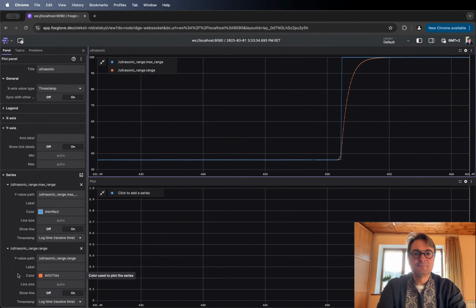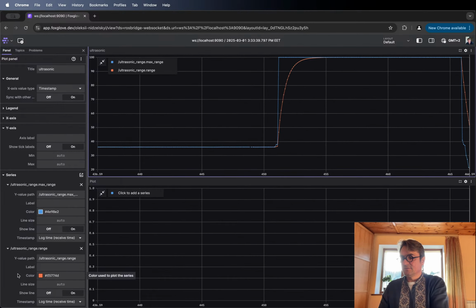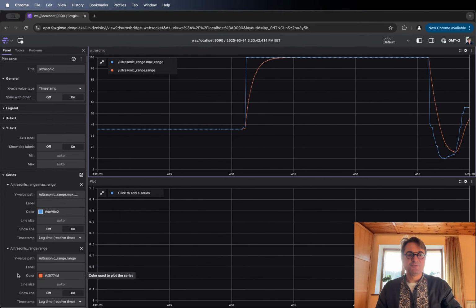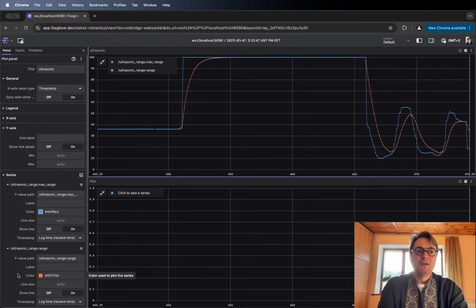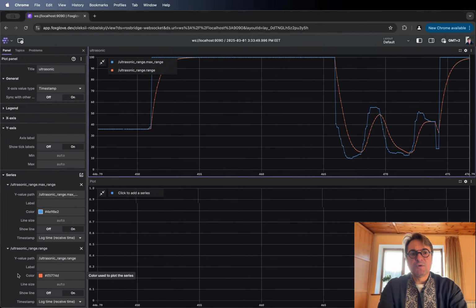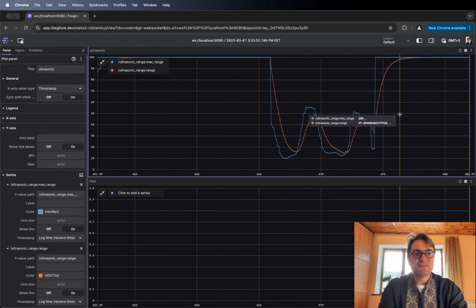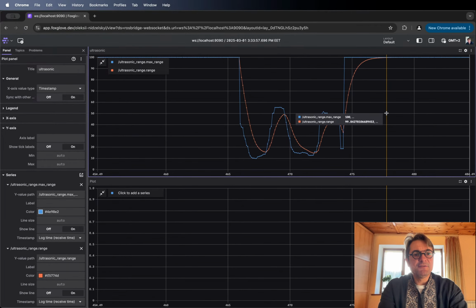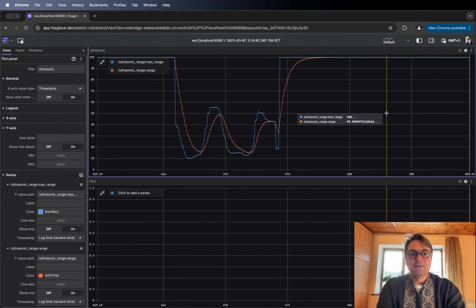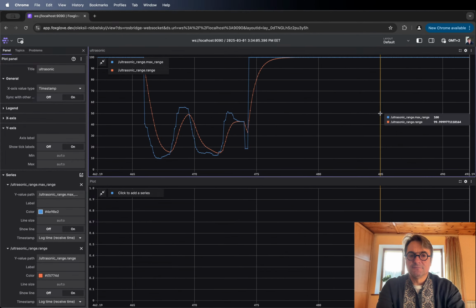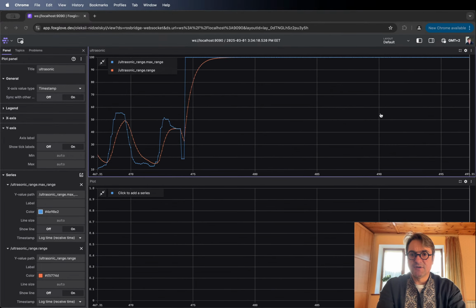So now if we move an obstacle in front of our robot, we see that this line changes. In our algorithm, we set that if the distance to the obstacle becomes less than 50 centimeters, we should stop moving our robot and start turning right. Okay, let's go back to our presentation.